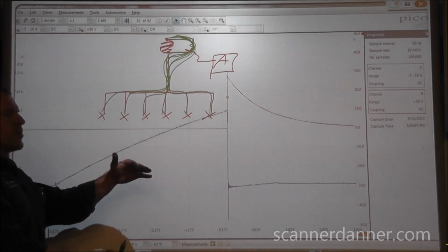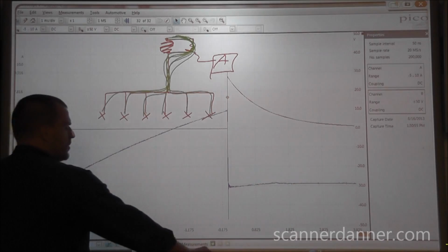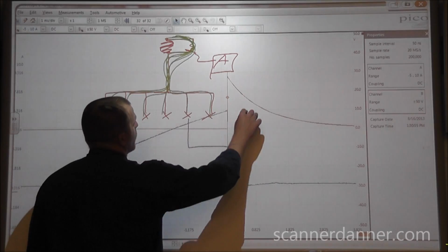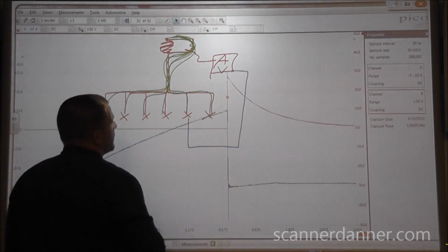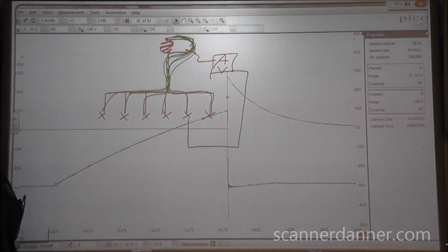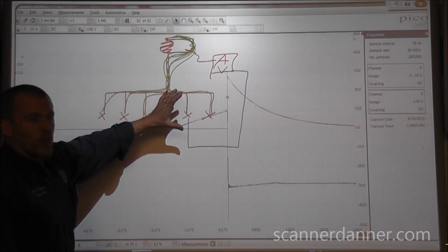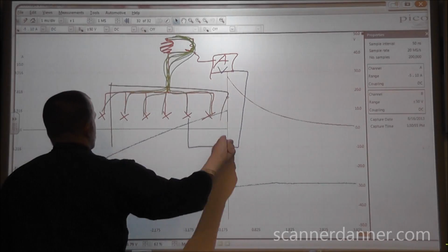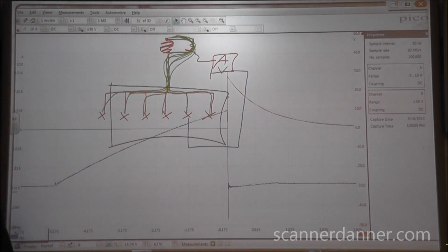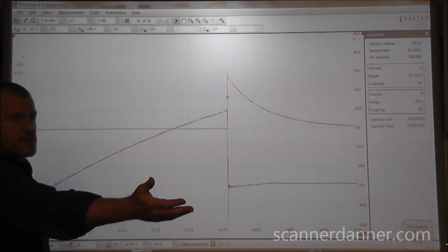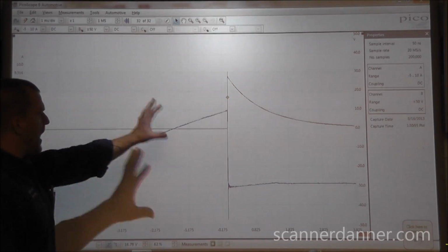If I have one particular coil that I want to focus on, what I can do is add a second channel, say synchronize off of one of these coils on a voltage waveform, and then I can figure out exactly which coil has an issue. I can zoom in maybe just on that one if I want to. When is this an advantage? When the intake manifold covers all of these. You need to know how to do this. And so, maybe not so relevant for a distributor engine like we're doing here, but at least you understand how to do that.